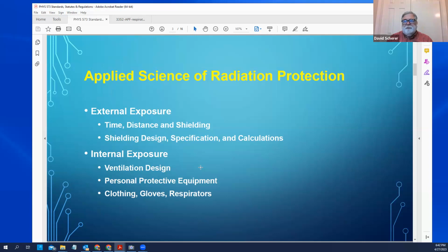PPE, personal protective equipment, which is our next item, should only be used for the residual hazards that can't practically be eliminated by engineering controls. Engineering controls are more reliable, and it's more difficult to circumvent them or to forget. The ventilation system operates, or should operate, effectively without you having to remember to do anything for it. That's the goal, at least.